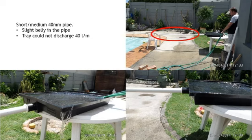Now look what happens with a belly in the pipe. It overflows all over the place. It couldn't hope to discharge 40 liters a minute. So that's a straight piece of pipe all of a sudden. No bends, 40 mil. Now we've reduced size to 40 mil. Okay, let's carry on and see what happened.